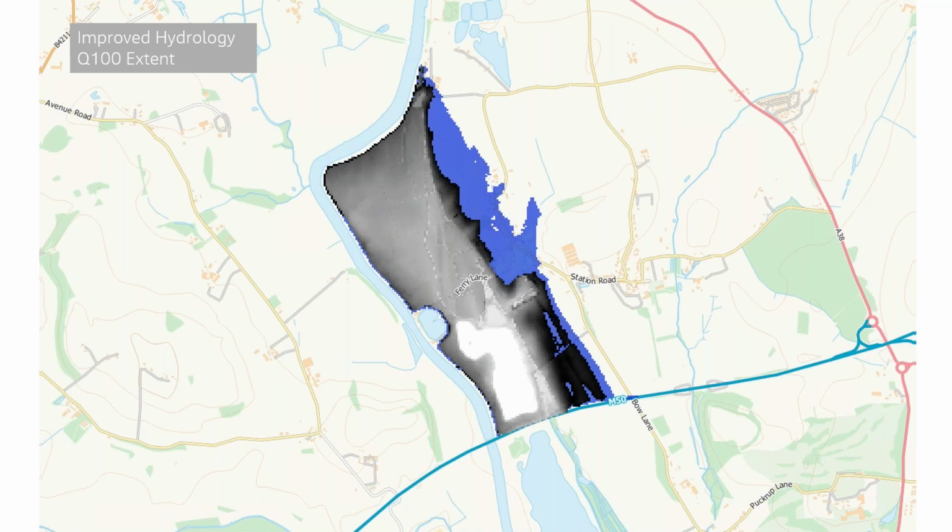Just adding an extra station into my analysis has changed the flood extents dramatically. I'm not saying that the Saxon Lode data is correct. There's obviously quality issues with it, but it demonstrates how much that can change the flow estimates.